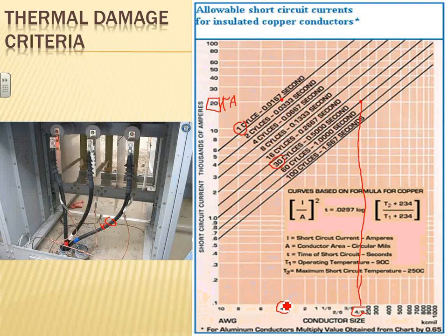And what's the available short circuit? Because when you have a medium voltage, it's not enough under normal operating condition. It will take care of business and cook your building for you. Under abnormal operating condition, you need to be able to restart your relays and clear the fault and clean what happened, and your conductor will continue to operate. You don't want to go pull your conductor because they're charred now.